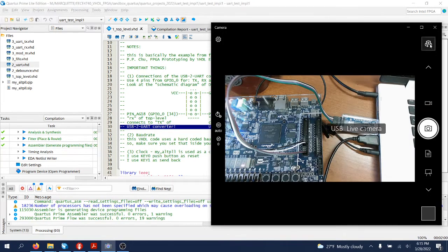the connections. So the connections are the VCC and ground, the first two coming here to the VCC and ground as I count from 1 to 6 connectors, and then, as I showed you, the bottommost ones of this converter are connected as shown over here to the TX and RX of the USB to UART controller.